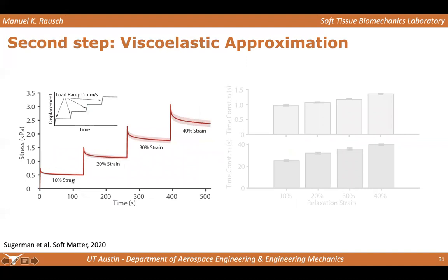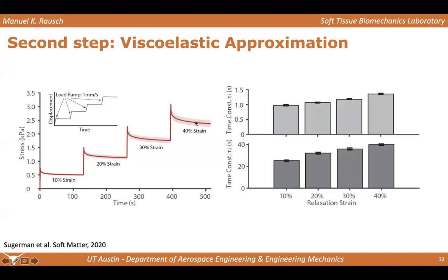And what we find is that, first of all, we have stress relaxation. I don't think that's surprising. And we did this actually in four steps. And then we quantified the time constants that determine this behavior. So we fit an exponential decay function with several terms. And we found that if you include two terms, you capture this behavior extremely well.